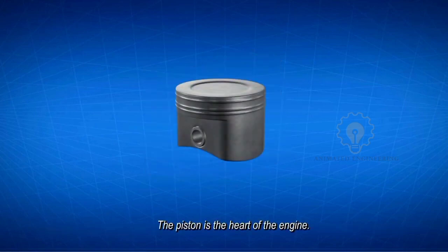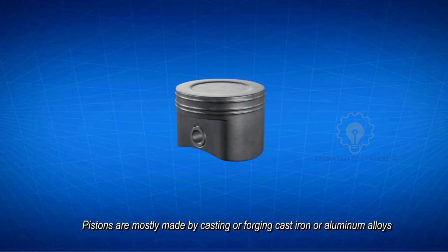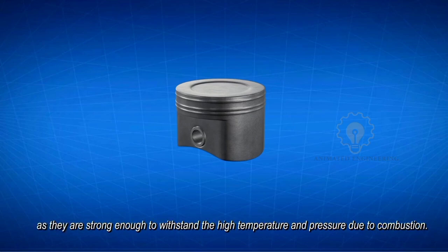Piston. The piston is the heart of the engine. Pistons are mostly made by casting or forging cast iron or aluminum alloys, as they are strong enough to withstand the high temperature and pressure generated due to combustion.